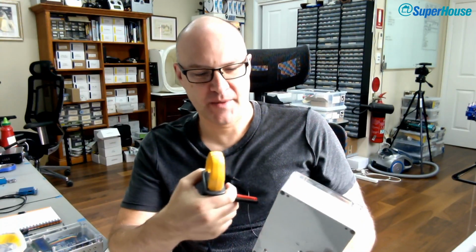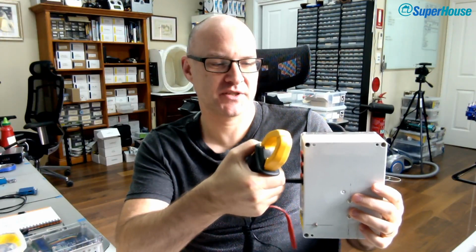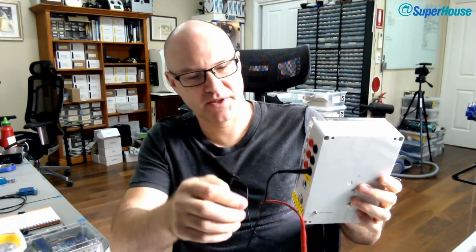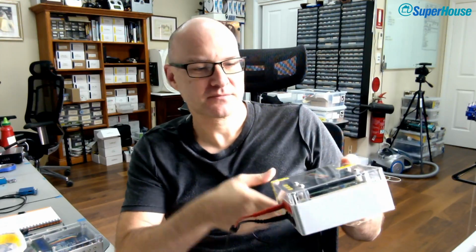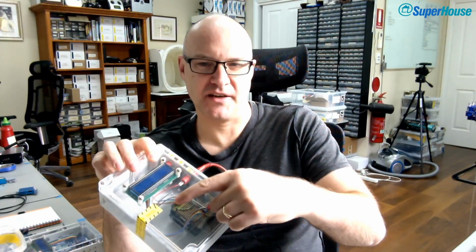So what happened with this is that we would just plug up to 3 of these current clamps into the box, and then that goes into analog inputs on the Arduino, and then we would read the voltage. The actual scale that comes out of this is selectable. It can be either 10 millivolts per amp or 1 millivolt per amp.